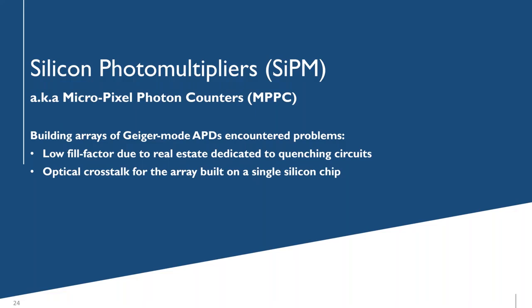The origin of this crosstalk is radiating transitions of avalanche electrons between sublevels in the conduction band. One can easily see such radiation under the microscope in the dark room. Biasing a single silicon APD at or slightly above the breakdown voltage, we can observe whitish bursts of light in the microscope. Of course, we have to limit the APD current when doing such experiment.